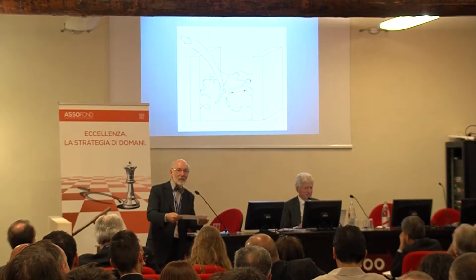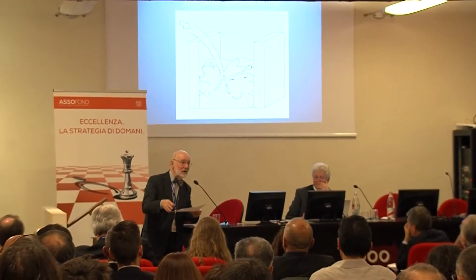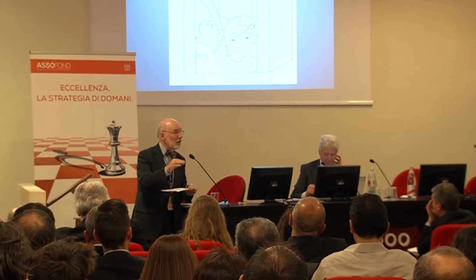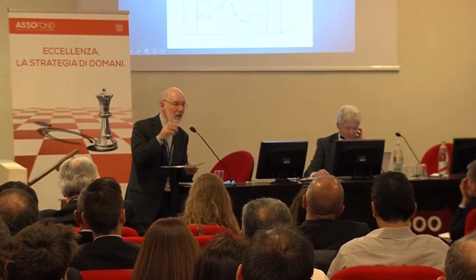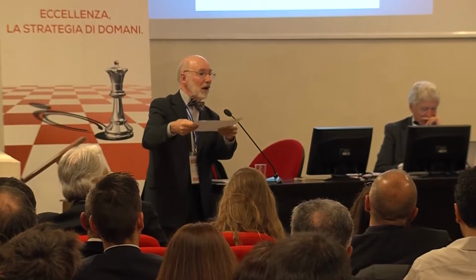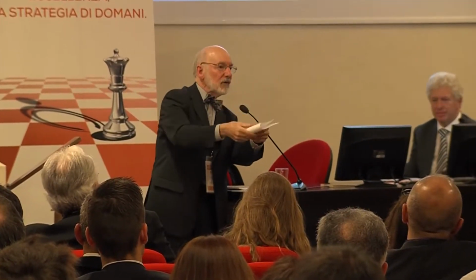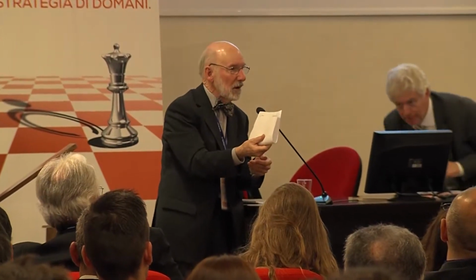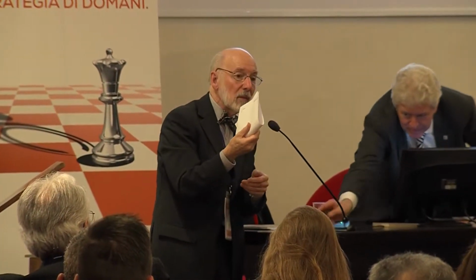so we see the metal coming up, it splits and moves to one side, and this gives us a good casting, free from oxides. But we never make castings like that. We pour the metal, and now we pour, and now the surface becomes folded over. Now, this is probably disaster, because now I have a dry side to dry side. There's no bonding between those two. So now I have a crack inside the liquid.